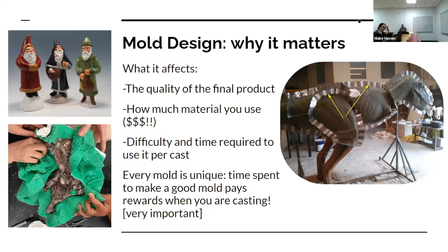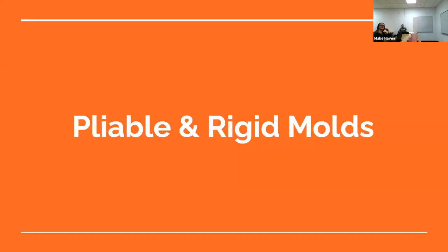Yeah, and that concept is essentially correct. I think I showed you guys a spreadsheet that I made when I was doing block molds, which is sort of a box filled with goo. When I went to figure out the amount of material I needed, I changed the minimum thickness of the mold walls by like 0.1 inches, and a single set of molds ended up costing me $200 more. It enlarges the overall volume of the box you're dealing with, and it's sort of hard to wrap your mind around that. I do have some examples here where I'll show you how much rubber it took to make a mold of this essentially skinny little thing, just because it was a strange shape. In any case, moving on.